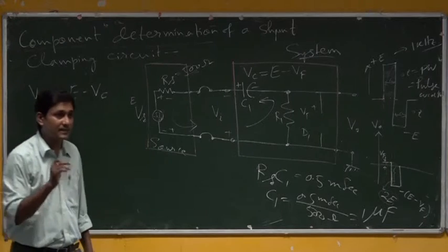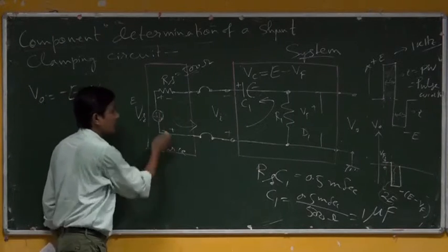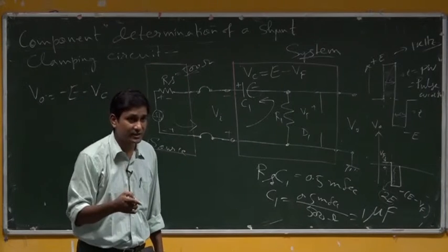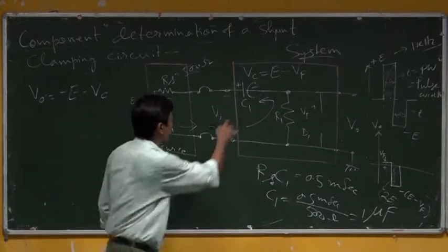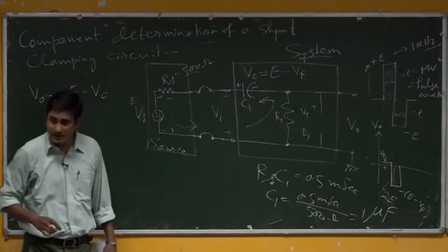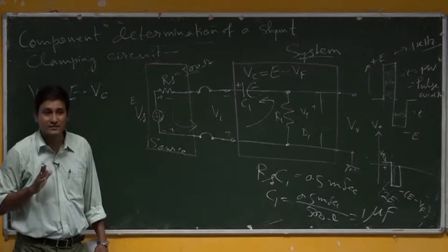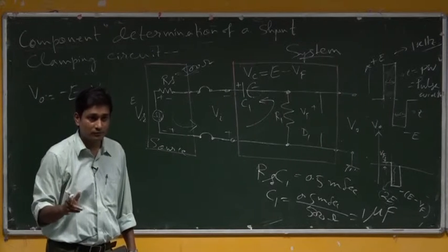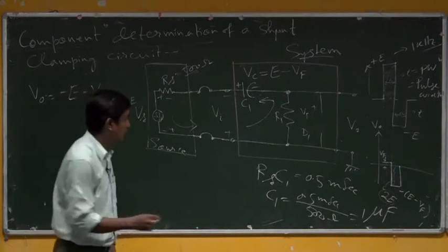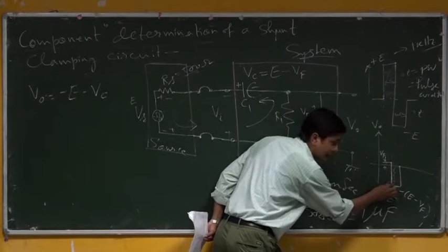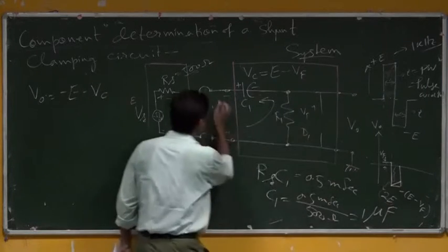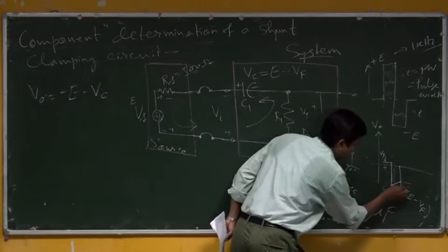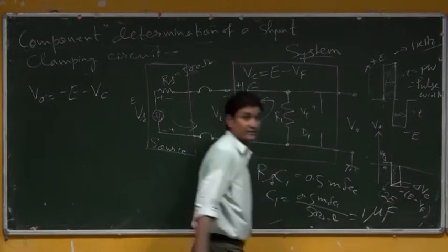because the capacitor has the behavior that it will like to track the potential to which it will be trying to get charged, so that the potential here becomes plus, here becomes minus. Whether the circuit will allow it or not, that is another issue. Okay. So in that we found that we went to a potential here, but slowly, because of this current flow inside it, some discharging was happening, and there we defined one delta Vc,